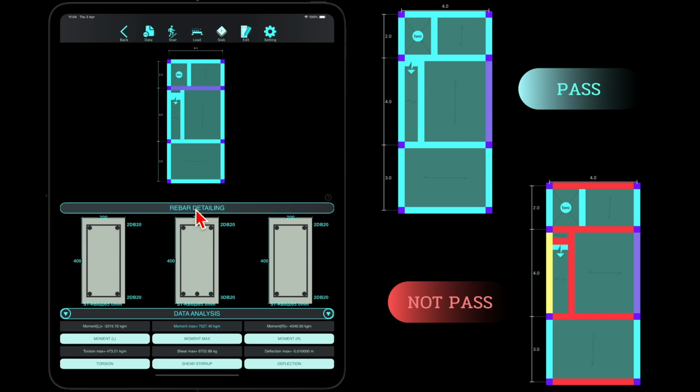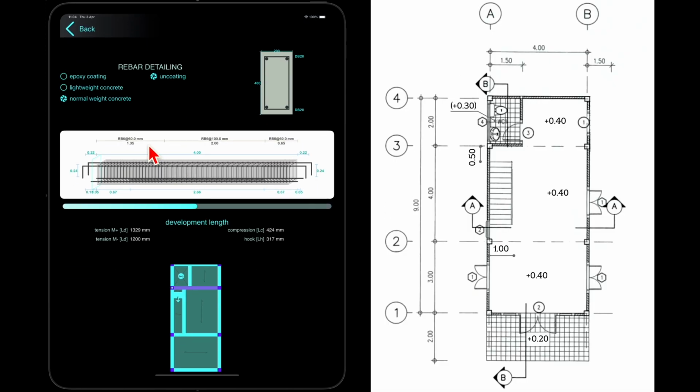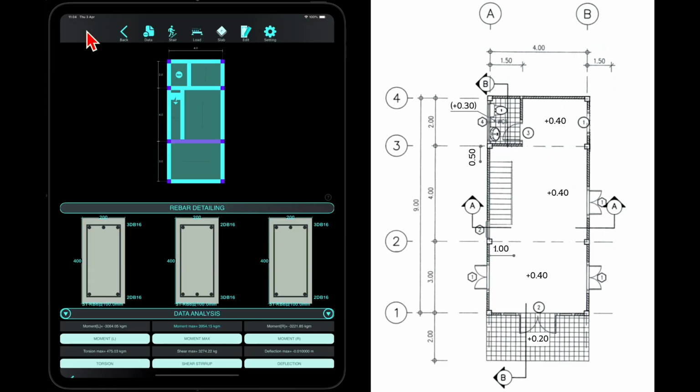Review reinforcement details. With detailed rebar specifications, we can optimize stirrup and reinforcement usage for greater cost efficiency. Things that can be done while maintaining safety include: 1. Using more frequent stirrups. 2. Using extended rebar lengths beyond the standard shown.